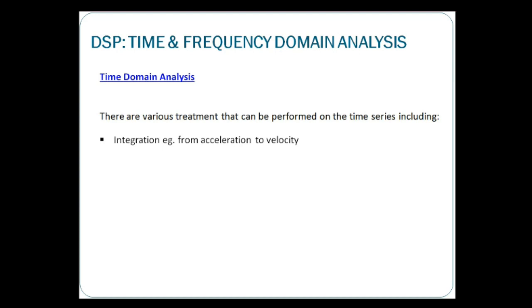So that allows us to use accelerometers now, and IEPE types. You see that, that is how convenient it is now. Using IEPE type, you have these built-in amplifiers, where you amplify the vibration signals, I mean, the signals in voltage, so that they can be read by these DAQs, right?